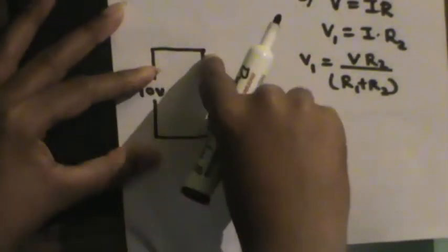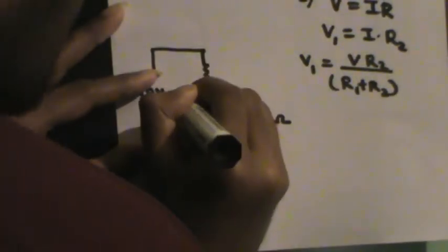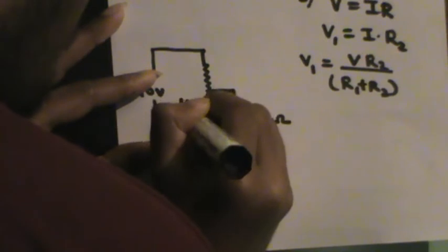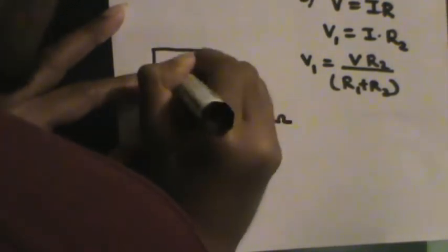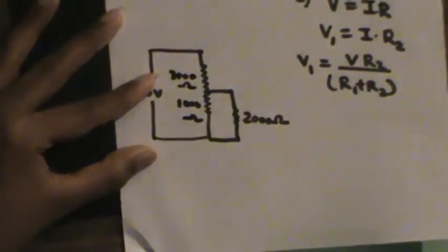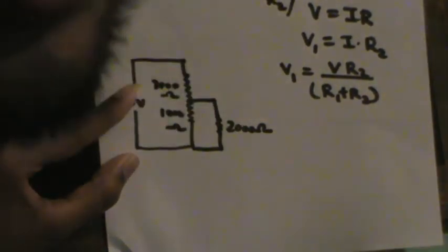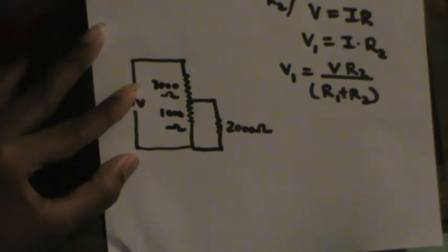resistor is connected at 1/4, since the total resistance across this is 4000 ohms, the resistance across this should be 1000 ohms, and resistance above this should be 3000 ohms, right? So what it is asking is, what is the potential difference across the load when the slider is 1/4 and halfway up the slider?